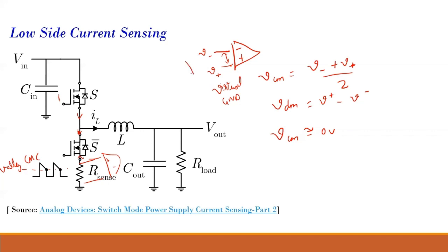There will be a very small difference. That is what is getting amplified in the differential amplifier. But it will be a very, very small, negligible value. So the common mode voltage in a magnitude sense is approximately 4 volts, assume. You don't need to be worried about 4.001 volt or 3.99 volt. That is not the thing. It is approximately 4 volt, you assume, and you proceed.